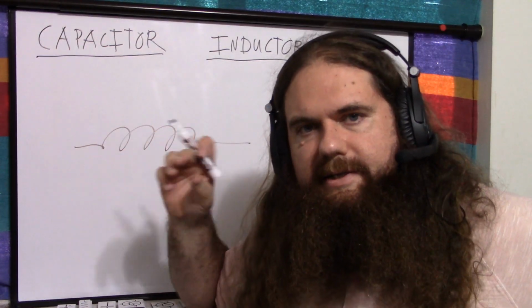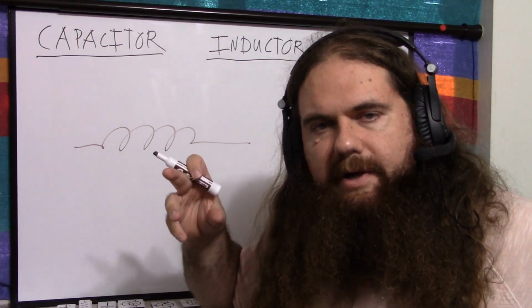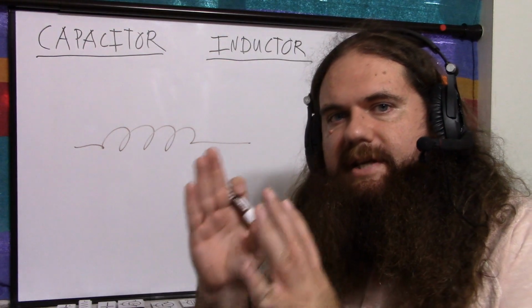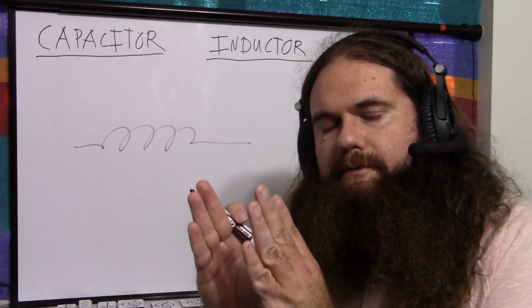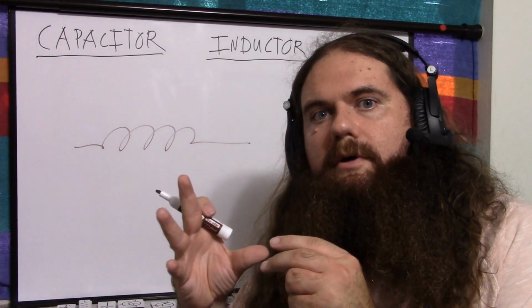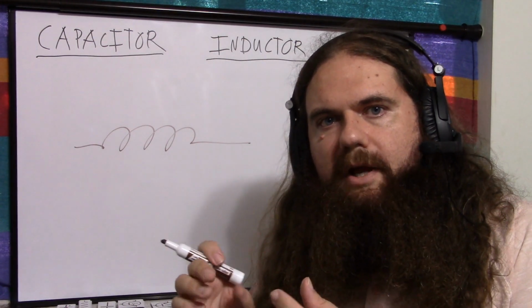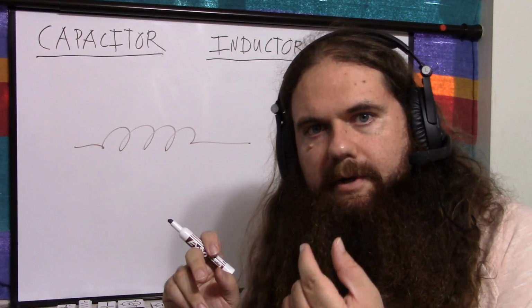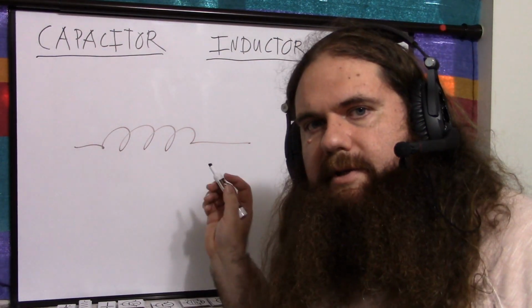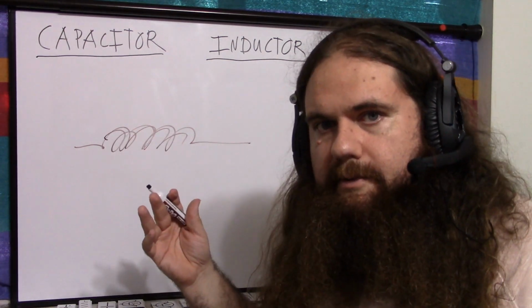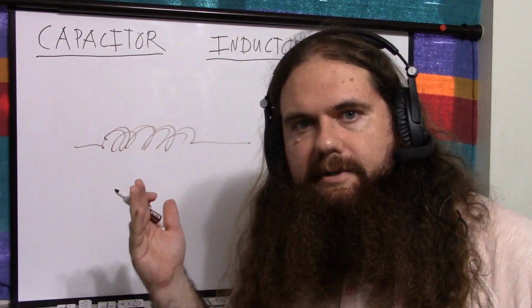Inductance, once again, is a measure of the capacity, just like a farad is for charge. If your inductance is higher, then for the same amount of current, not voltage, but current, the magnetic field is basically going to be stronger. For 1 amp, 2 amp, 3 amp, you're going to have more magnetic strength in there for the same current. If you make it longer, the inductance goes down. If you add coils, the inductance goes up. And if you make it thicker, the inductance goes up.